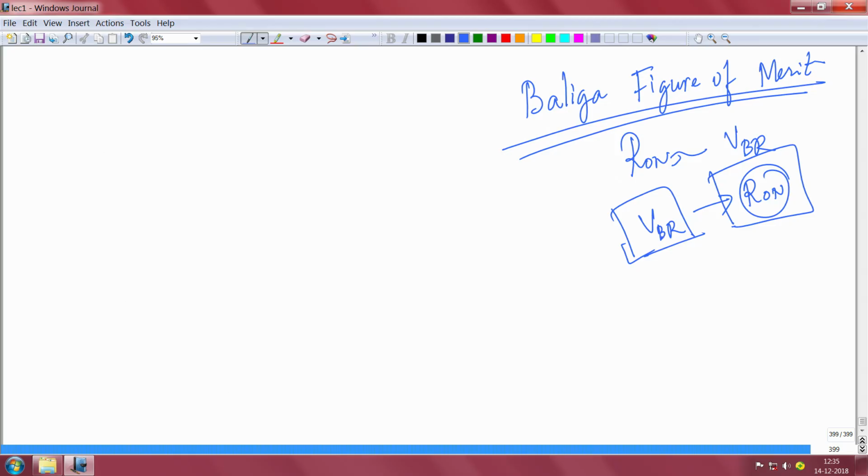You have to sacrifice one for the sake of the other, and there is a limit to it which is defined strictly by the material parameters like mobility and the critical electric field, which is a material-dependent property, and so on. Okay. So these devices are used for switching, and because you can block the voltage, you can let current go, and this switching has huge applications in DC-DC conversion, power conversion, DC to AC conversion, AC to DC conversion.